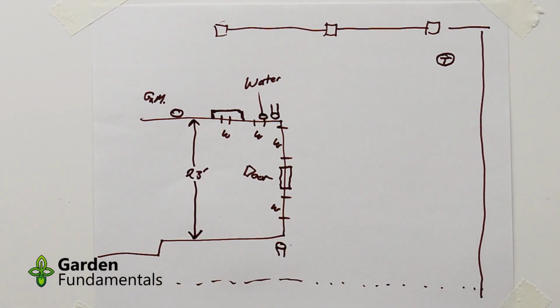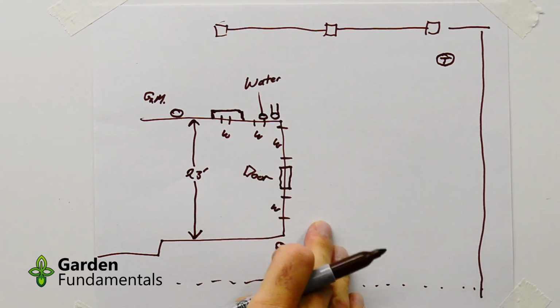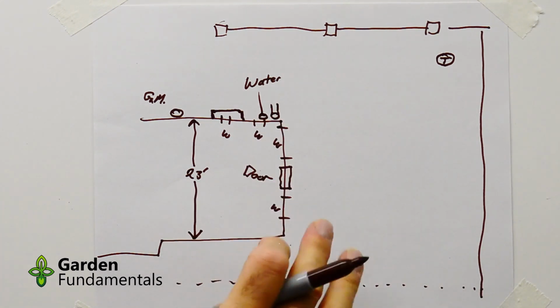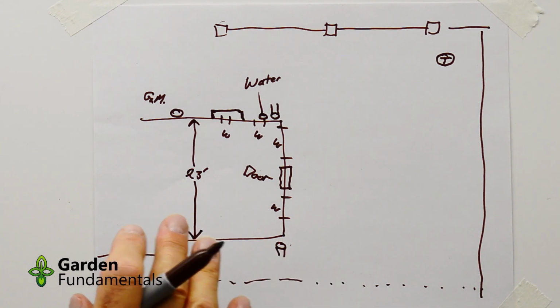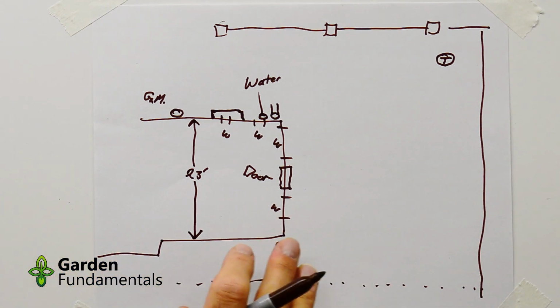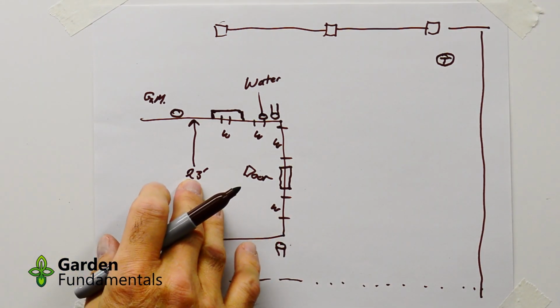So that's the width of the house. Now, how accurate do you need to make these measurements? For the kind of design we're going to do, plus or minus a foot is close enough. When you actually go and do some construction, if I'm going to put a deck at the back of the house, I'm going to want to measure this a little more accurately to make sure it fits. But for the purpose of the design process, to the closest foot is accurate enough.